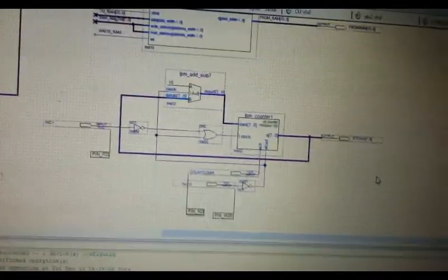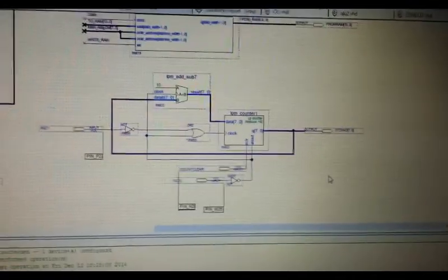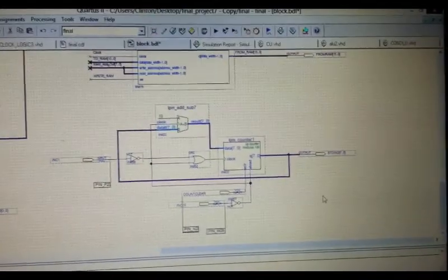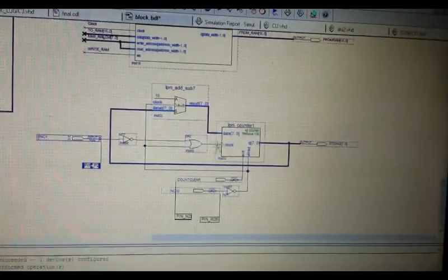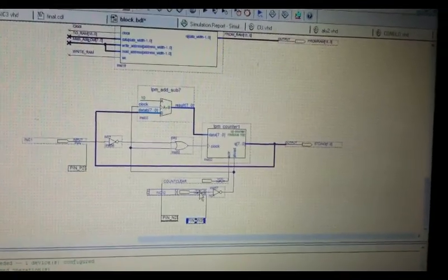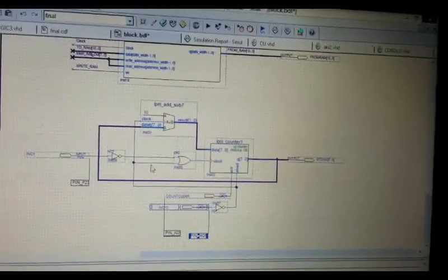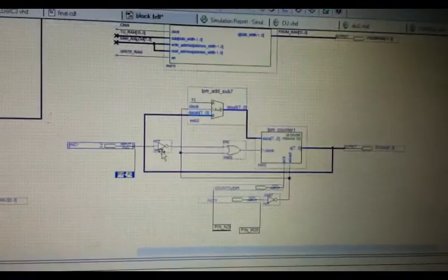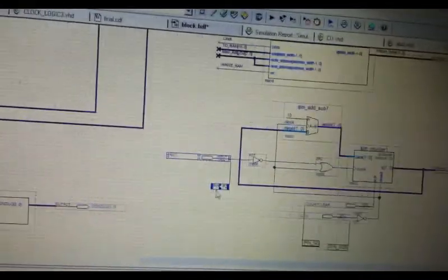And right here is just the logic for the SDN. All it is, is a counter that is connected to an adder, basically. The output of the counter is connected to this adder right here. If you press this button right here, it increments it by 1, but if you press this button right here, it will increment it by 10. And the signal is just connected to this OR gate, which is also ORed with the increment once signal, and that drives the clock. So nothing too fancy, just a quick solution.